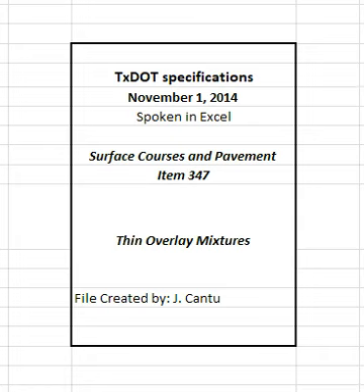4.4.2.1.9 Trial Batch Production Equipment. Use only equipment and materials proposed for use on the project to produce the trial batch. 4.4.2.1.10 Trial Batch Quantity. Produce enough quantity of the trial batch to ensure that the mixture meets the specification requirements. 4.4.2.1.11 Number of trial batches. Produce trial batches as necessary to obtain a mixture that meets the specification requirements.